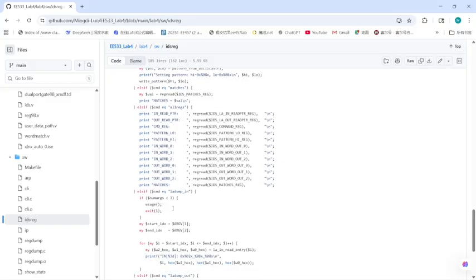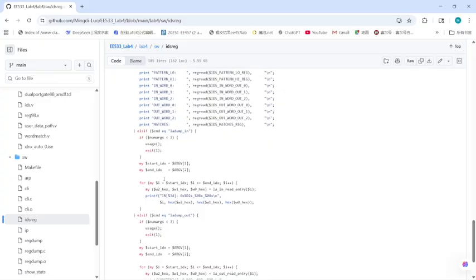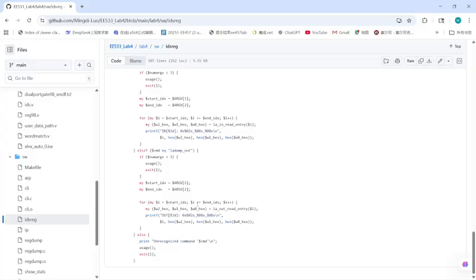The LA dump in and the LA dump out commands are used to dump the data captured by the logic analyzer. So all the functions are fulfilled here. After the user specifies the start and end indices, the script sequentially sets the read pointer and reads the corresponding 72-bit captured data, which is split into 3 32-bit registers I've just told you about, and outputs the control field and the data field in a formatted manner. Okay.